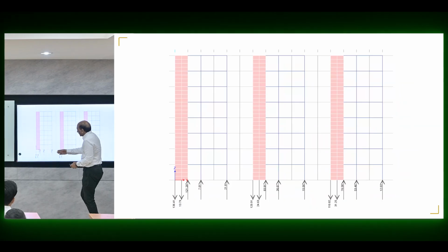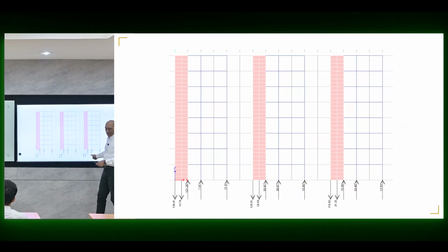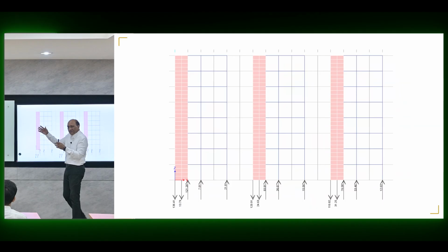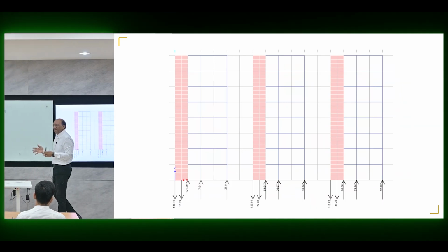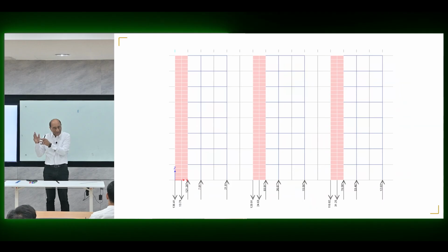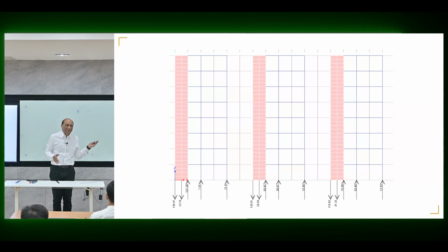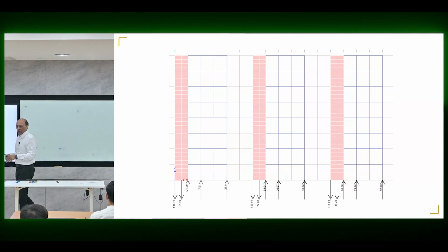Okay. Now you can see also that the column reaction will change. The next column goes from 7 to 36 to 53 axial load. So that means the foundation and everything will change. As soon as you put the coupling, the whole distribution of axial forces changes. And this is back to our concept. Strategy number 1, convert bending moment into axial forces. So the coupling helps to do that. It converts the bending moment into axial load, which is much more efficient that way.